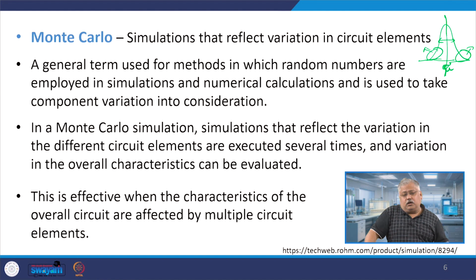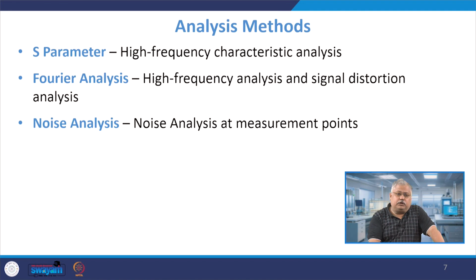The third point of Monte Carlo is that you require a very large amount of data in order to justify the Monte Carlo simulation. If there are say just 4 variations, then it will not give you a proper Gaussian output. But if you have 10,000 ensemble points where you are doing it, you will obviously get a very good Monte Carlo output simulation. So, when circuit designers use EDA tools, they invariably run Monte Carlo variations and try to formulate the output characteristics of the device.